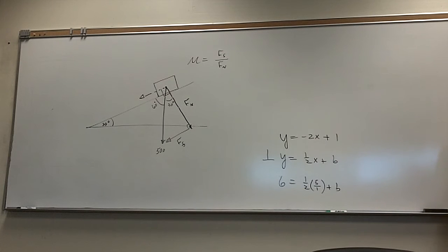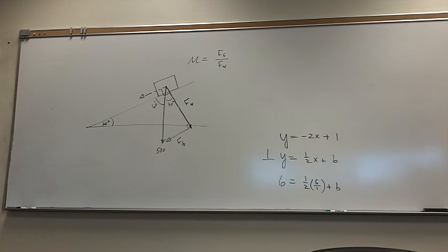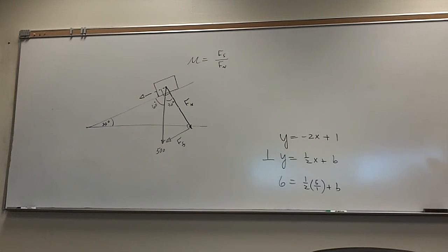Now, you're going to find that there are two of them. There's static friction, and there's also kinetic friction, the friction of motion. Static friction is the value it takes to start something moving. And you know as well as I know, it takes more force to get something moving than it does to keep it moving. That extra value it takes to get it moving is called the static frictional value.